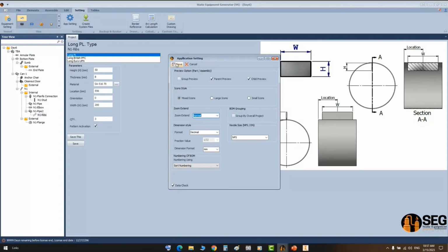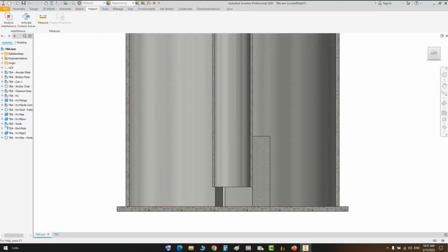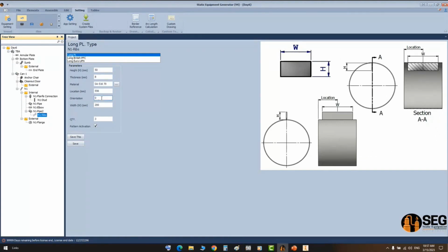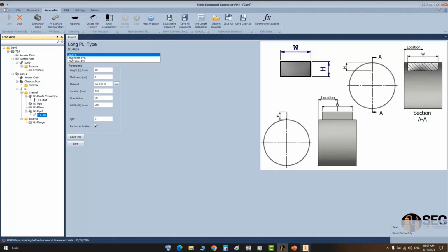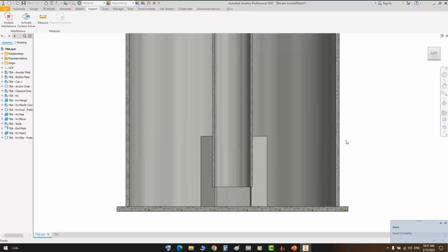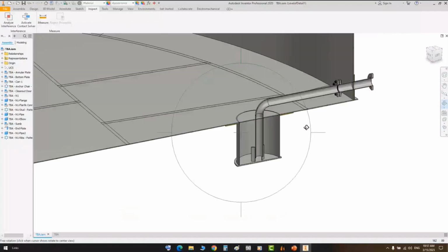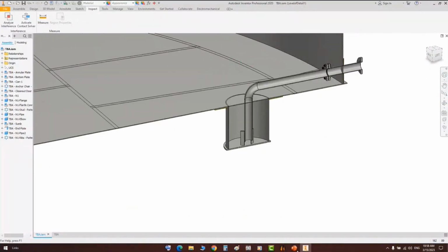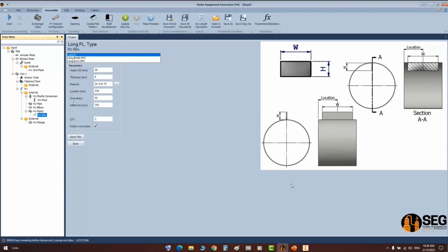So if you select normal, now when you make a zoom like that and make a modification in anything, like changing the orientation to make it, for example, 5 degrees, or 0 degree, 90 degree, and click on Save, now when you click Start Assembly, the zoom out will not take place when you make the assembly, so the view will keep as it is, no automatic zoom extend, unless you make the zoom by using the orbit option or using the view cube.